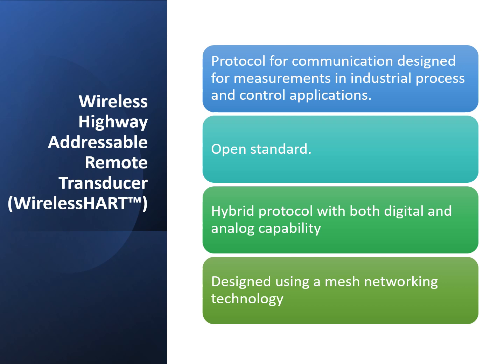The protocol is referred to as a hybrid protocol in that it combines both digital and analog communication. The HART protocol can communicate one variable through the use of a 4-20 milliamp analog signal, while at the same time communicating added information on the superimposed digital signal on the current loop.